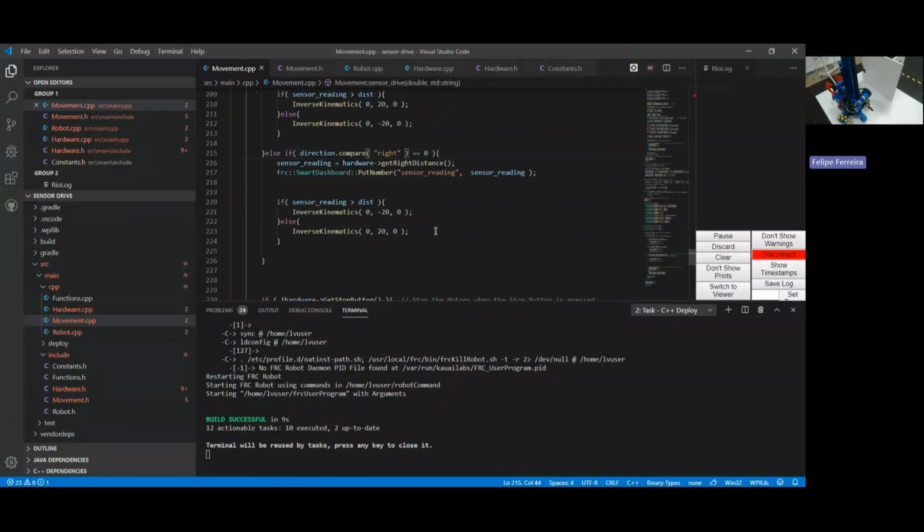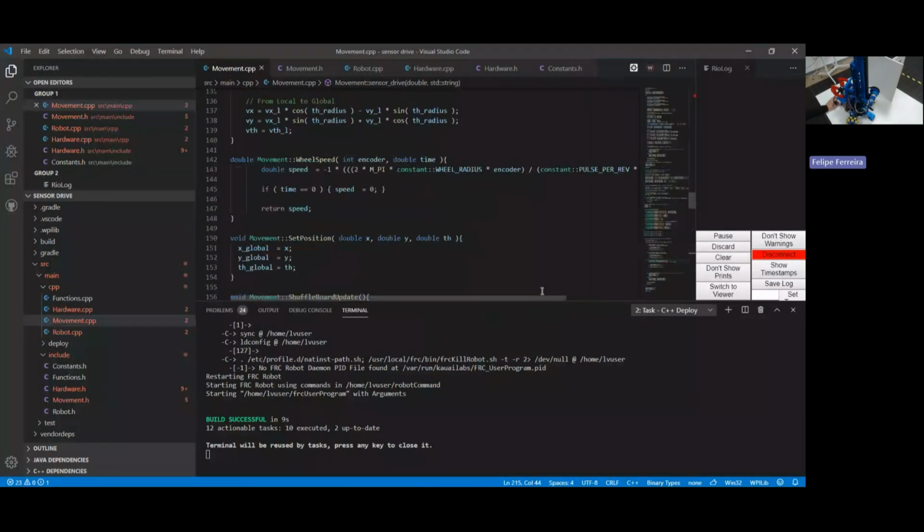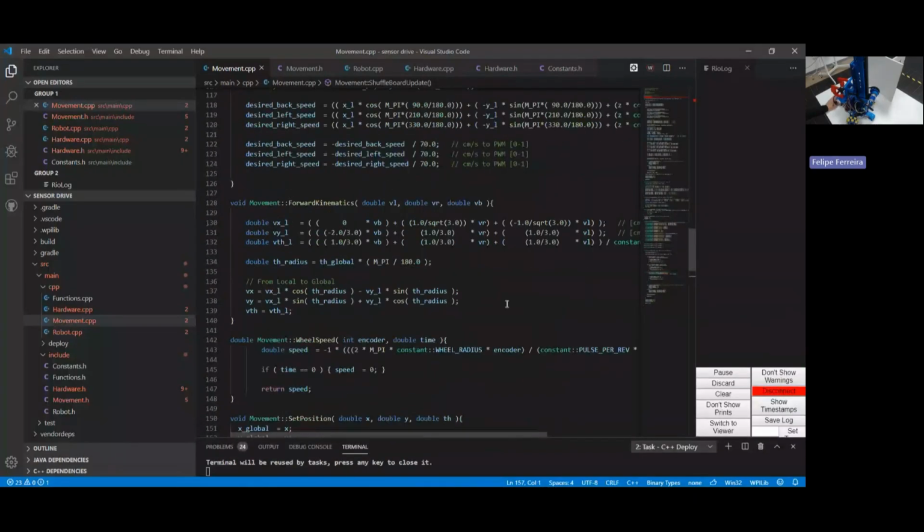This robot has an issue with the balance of its weight. The weight on the back is different from the weight in front. In front, the weight is much higher than on the back, so the back rotates more. This code here I made as simple as possible. It means that I don't have a PID control.